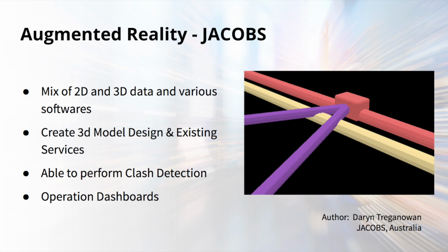As such, they sought to combine the different data sets into a singular GIS service model. This meant for the design pipes and services, the CAD files that had annotation only and no attribution, they would be required to associate the annotation text to the line work to create smart lines, basically lines with information. Designs often display multiple lines as a single line in CAD, as the center of the trench, basically. This had to be corrected to produce an accurate model, done by using information located in the text.